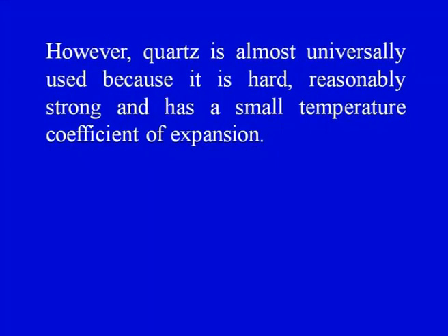Out of these substances, Rochelle salt is the most active crystal, generating greatest potential difference for a given mechanical stress. However, quartz is almost universally used because it is hard, reasonably strong, and most interestingly has a small temperature coefficient of expansion.